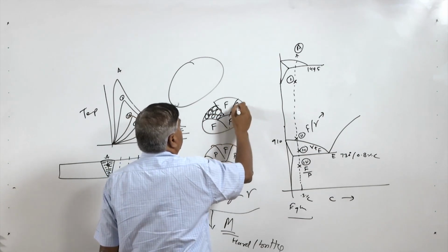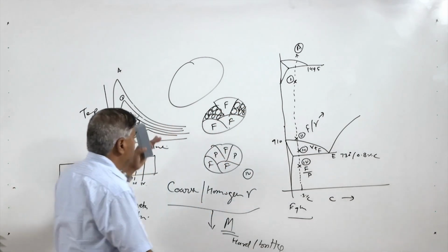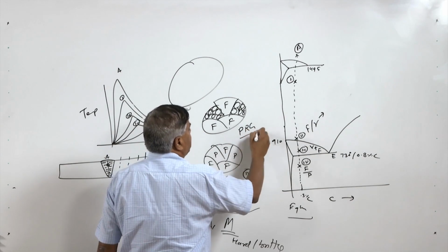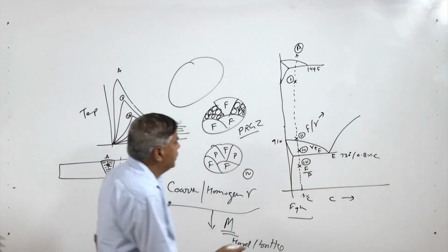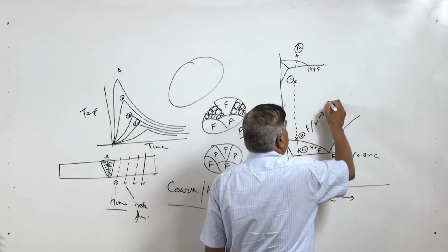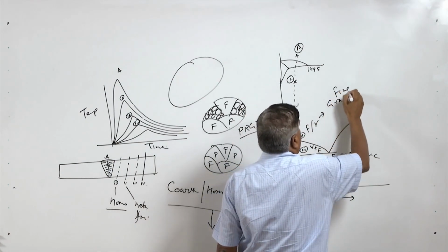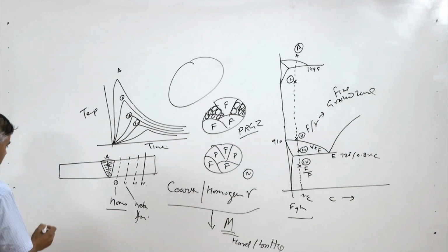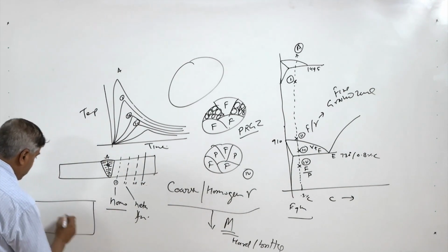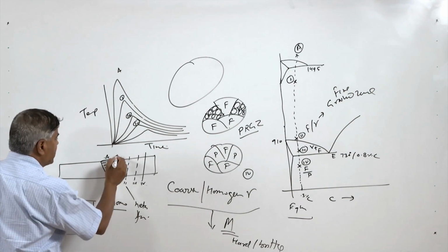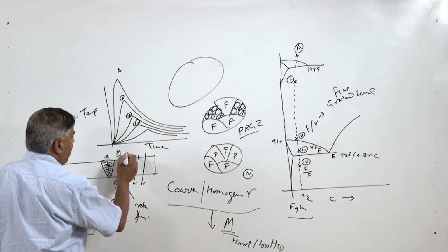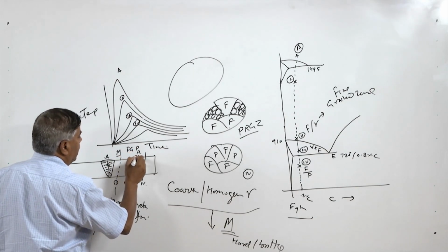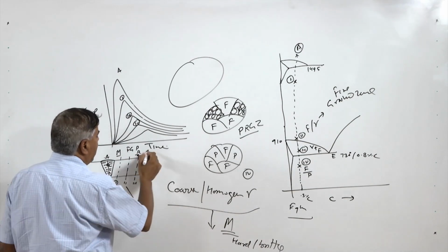So this zone results in the formation of the partially refined grain zone, while zone 2 results in the very fine grained zone. As far as the weld of the steel is concerned, welding may result in martensite formation, then we will have the fine grained zone formation, then the partially refined grain zone formation, and then the unaffected base metal.